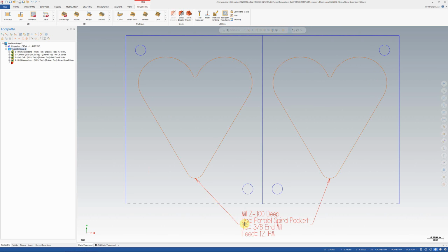We're going to choose a drill and come back, and that's going to pre-drill the holes, and then we're going to grab a reamer, and the reamer is going to size the holes to the 4th place decimal, making it an accurate tight fit. The other tool that we're going to use is, come back to our first tool, which is the spotting tool. We're going to actually use that same tool as an engraving tool, and we're going to engrave a scribed line down the center of the mold so that you know where to line it up on the bandsaw when you split your mold in half.